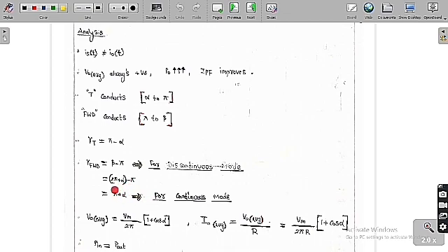For continuous conduction mode, the current will never be equal to 0. So simply we can say that from 0 to alpha, the freewheeling diode is going to conduct. Again from pi to 2 pi also, it is going to conduct. So listen carefully. From 0 to alpha the freewheeling diode conducts, and again from pi to 2 pi the freewheeling diode conducts. So the overall range is pi plus alpha. For a period of pi plus alpha the freewheeling diode is going to conduct, whereas for the range pi minus alpha we conduct the main thyristor.